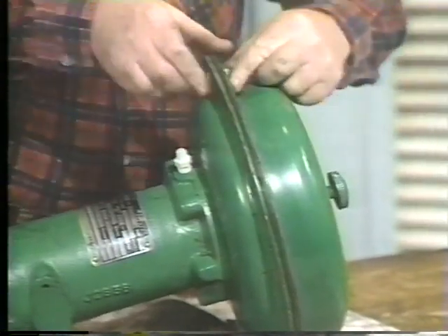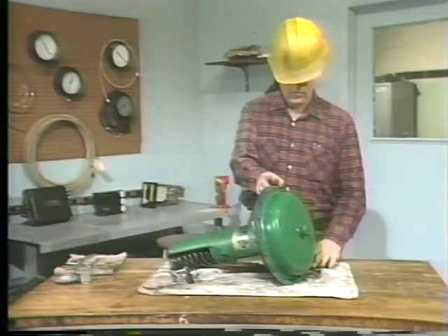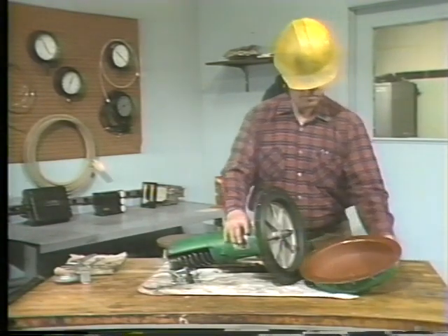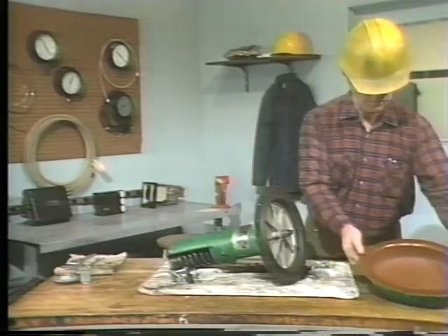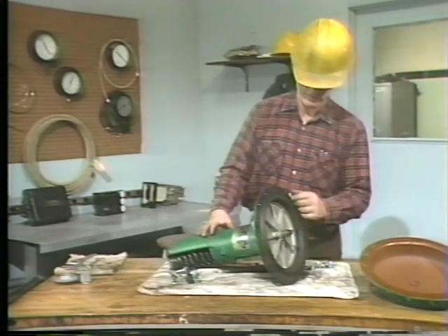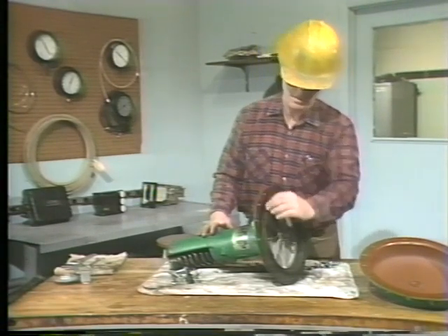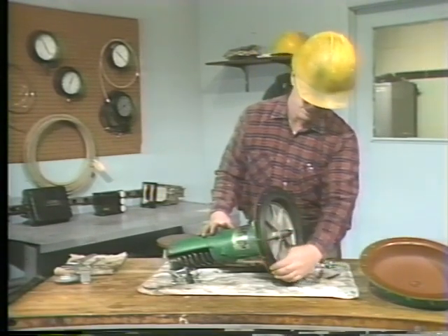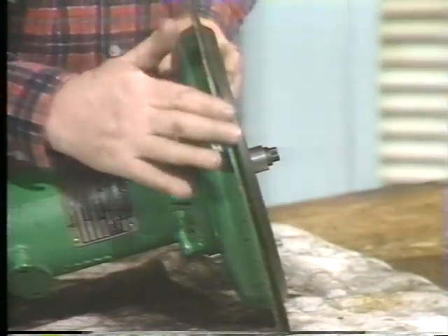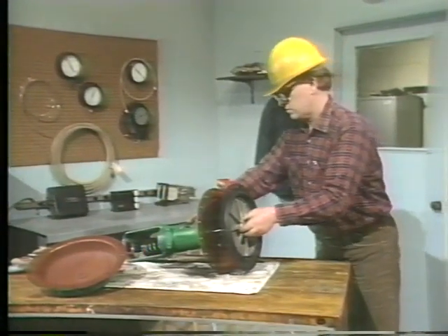Both sections of the diaphragm casing are bolted firmly together at the flange to form an airtight seal. If the flange on either the upper or lower casing is bent or cracked in any way, it must be repaired or replaced to ensure that the actuator doesn't develop air leaks. Also, the flanges must be clean and free of corrosion, which could also cause air leaks. Once the technician has inspected the flanges, he can now remove the entire diaphragm and stem assembly.